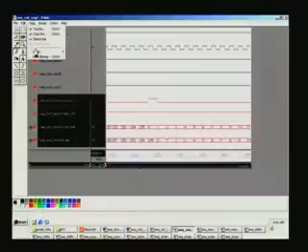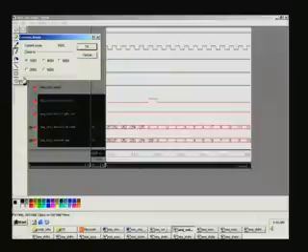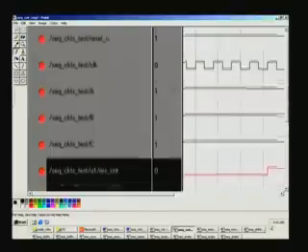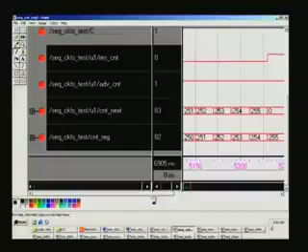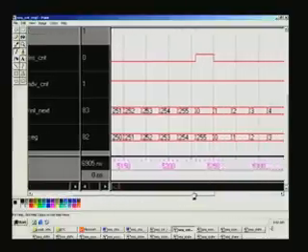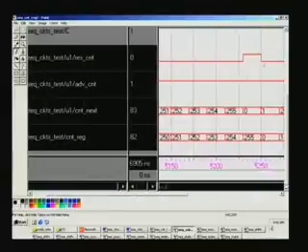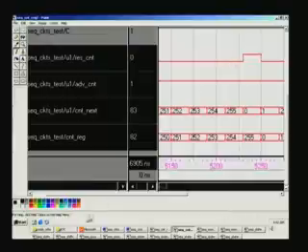Just to zoom in here, so you can see this here. The last two are the counters. You can see 250 is the counter edge, and pre-increment is 251, and this happens to be reset count here, and advance count continues to be 1. Therefore, it is counting. Had it gone to 0, it would have reset. So, that is how you see that the counter is working.